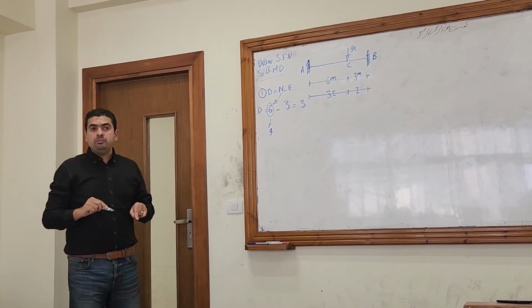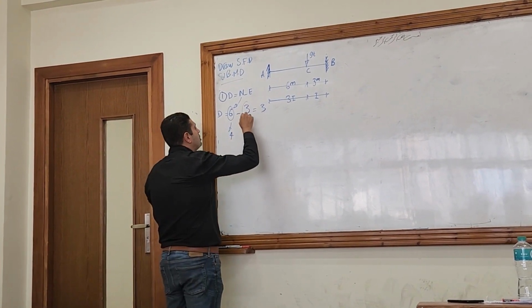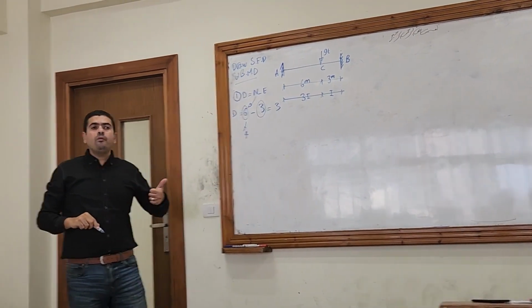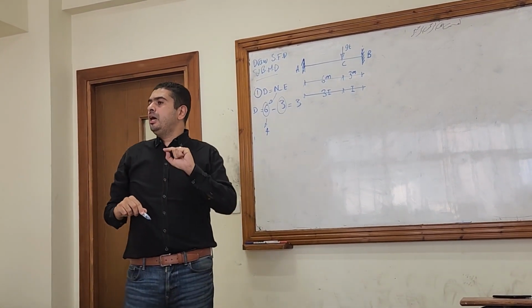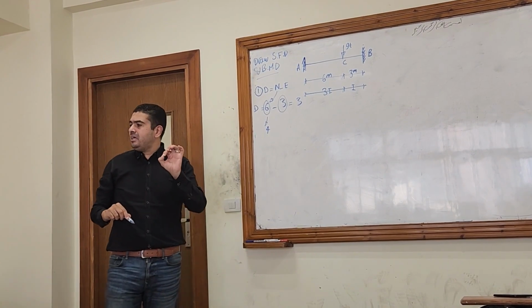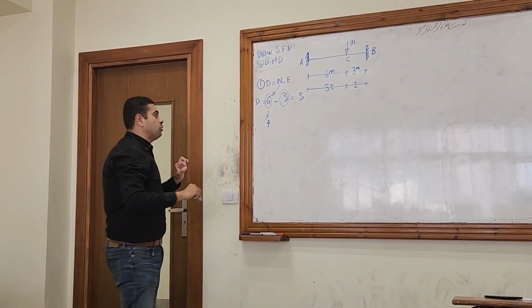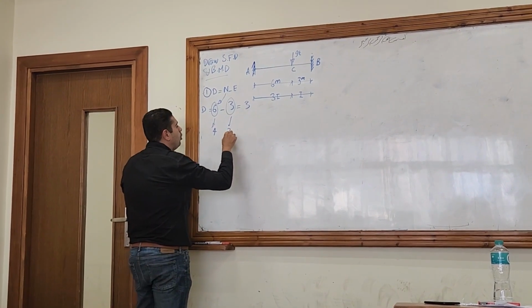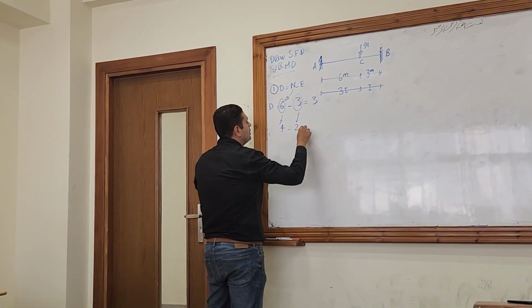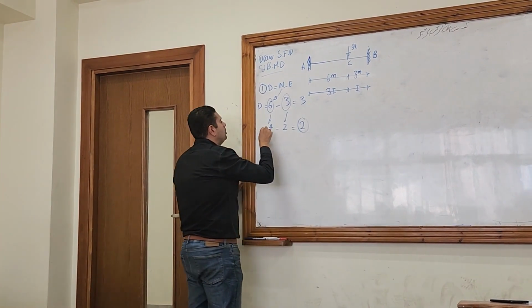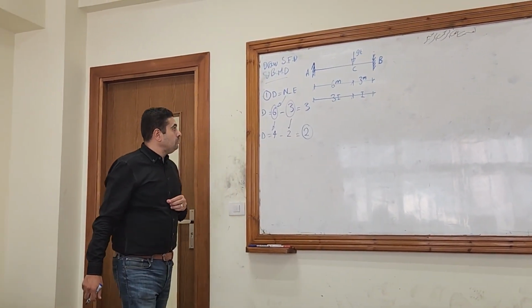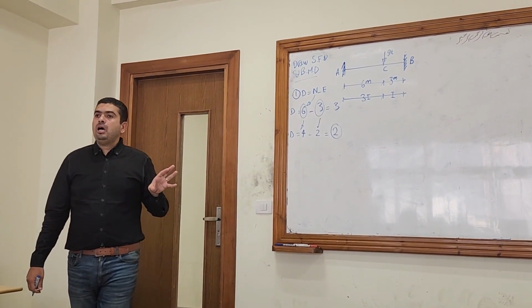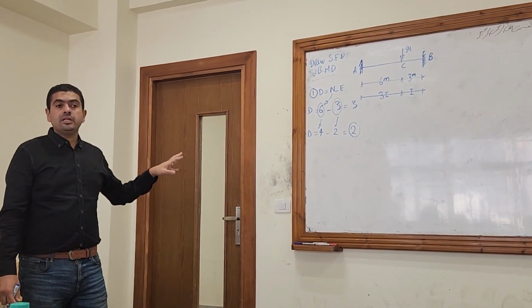But at the same time, the equations will not be 3. You remove the horizontal reactions from the redundants, so remove the equation of sigma x equals 0 from the equations. So the 3 equations will be only 2. So the right degree here is 2, not 3. So this will be the first step, how to calculate the degree of indeterminacy.